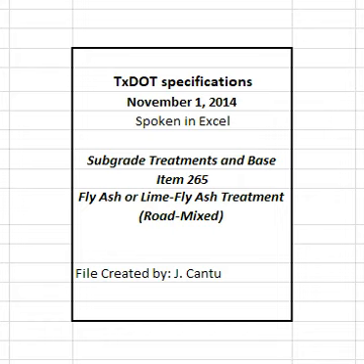Suspend operations when the engineer determines that weather conditions are unsuitable. Minimize dust and scattering by wind. Do not apply lime or FA when wind conditions, in the opinion of the engineer, cause blowing lime or FA to become dangerous to traffic or objectionable to adjacent property owners. During the interval between application and mixing, sections treated with hydrated lime or fly ash that have been exposed to the open air for a period of 6 hours or more, or that experience excessive loss due to washing or blowing, will not be accepted for payment.